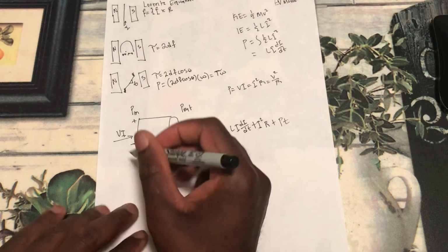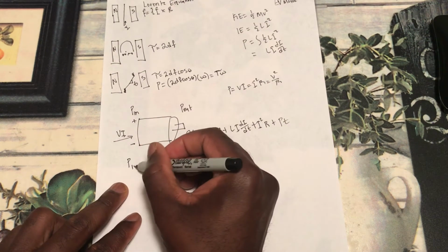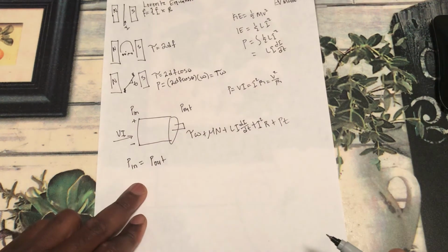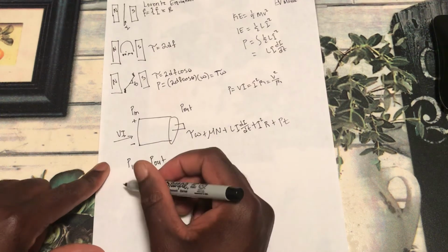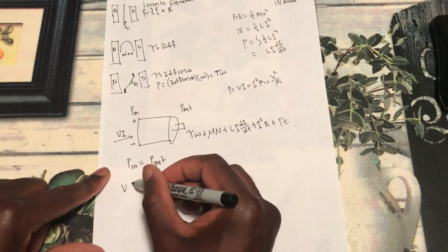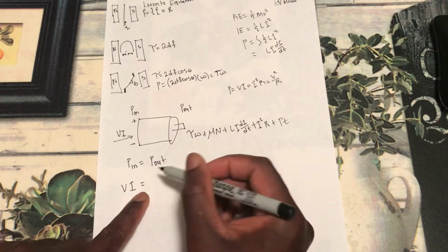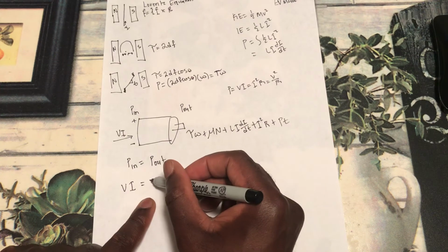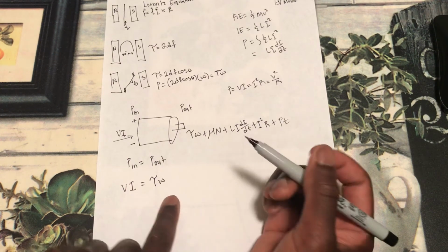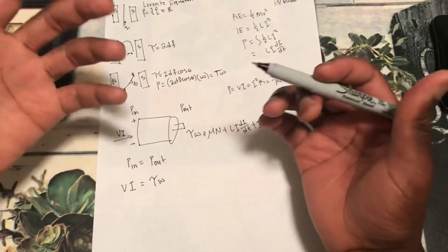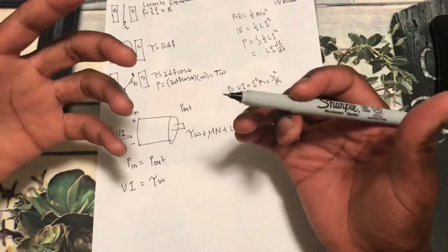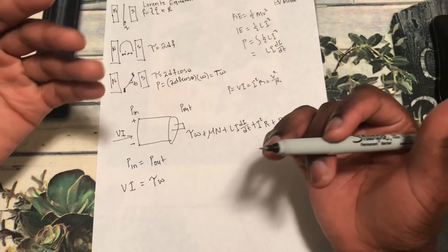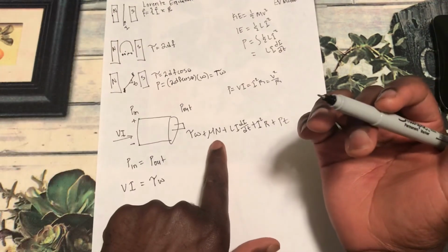So from here, we simply set up our equation. P in should equal P out. Again, what goes in is simply the electrical power, which is the voltage times the current, and what comes out is power due to mechanical work, torque times omega. Oh, another thing, we can assume that our motor is efficient to a point that the power loss due to friction can be considered negligible.